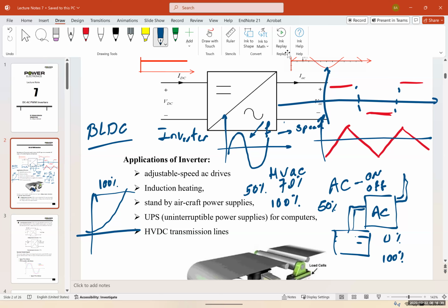The first generation EVs, like the Tesla Roadster, used a DC motor, for example. Some of those early adopters used DC, and they realized quickly that with DC you have a lot of loss. DC motors are more expensive. AC motors are much cheaper, actually. And they switched to permanent magnet motors, a type of AC motor that uses permanent magnets. But the problem was controlling the speed, and therefore the inverters came into the picture there.